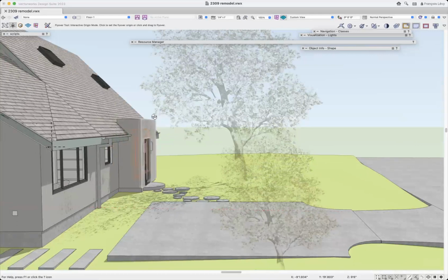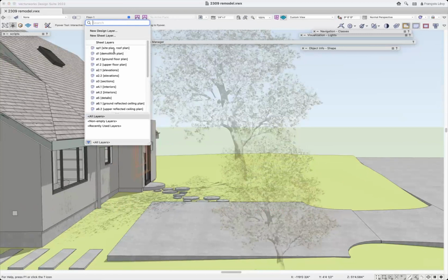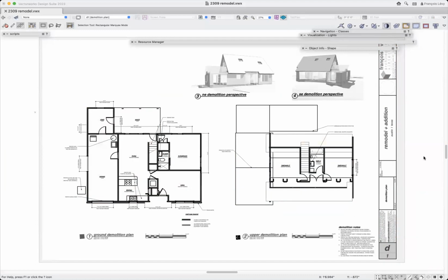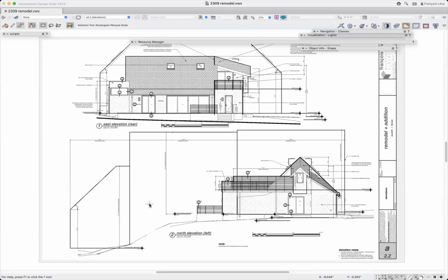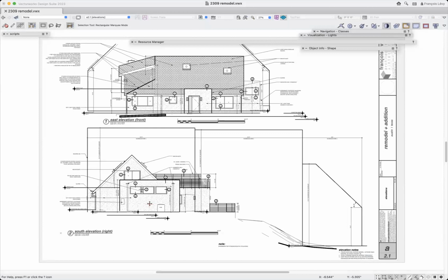Yeah, so the short answer is that most of my drawings, if I go to the CDs, I'll go in black and white mode. And if I just flip through the CDs, I could have a slightly different stipple pattern for the new stucco versus the existing stucco. But I'm not really sure who that's going to serve, because by the time the stucco contractor gets there, it's all just one wall to them. They don't know the difference. So really the distinction is important for the framer, more than anything else. For understanding the bidding process.